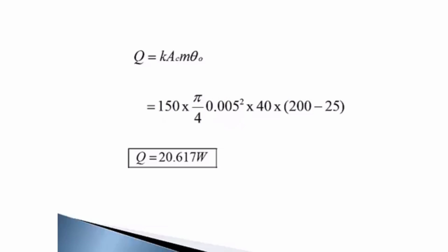Once you get the temperature difference, you will be able to find out the temperature also. In some cases, they may not state it as a long fin, but seeing the situation, the length, the thermal conductivity, all that, you should decide whether it is a long fin, short fin, or fin with the end insulated.